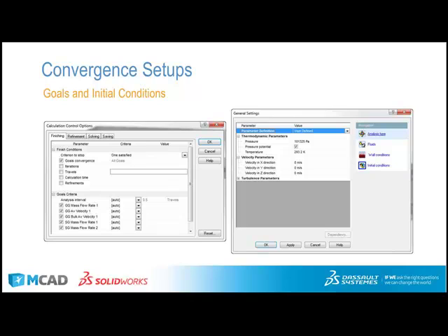So I started at the lower end, and I just gave the entire channel a forward velocity of 8 meters per second. The idea is that if I set it to an average condition, the solver doesn't have to allow the entire body to come up to speed. It's already moving, and it can iterate from that value instead.